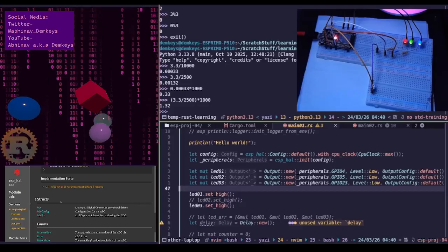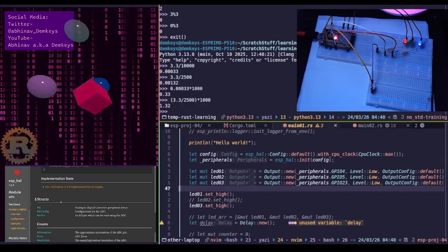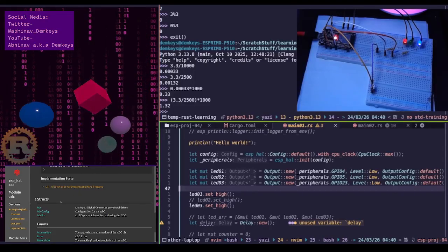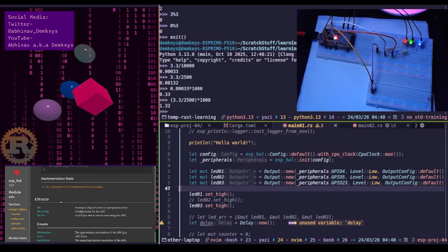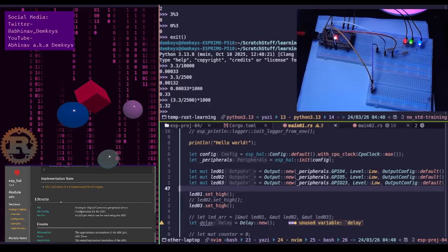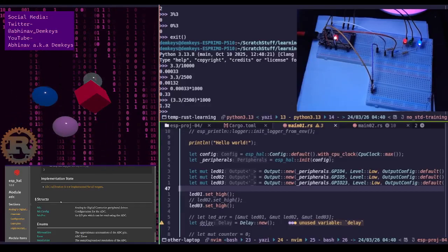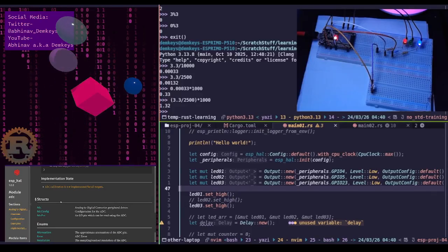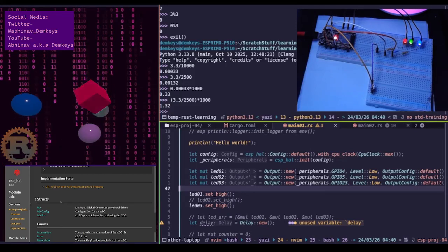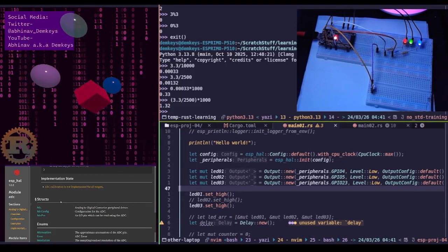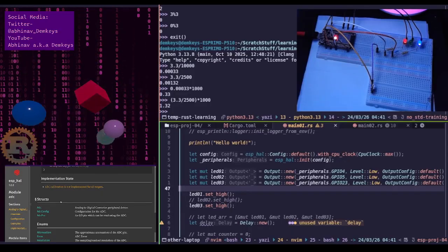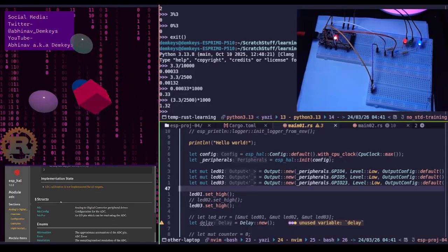Anyways, okay. You are exactly right. A voltage divider is for information, not for power. In the world of microcontrollers, we use them almost exclusively as sensors. The loading problem, why it fails for power. The reason a voltage divider doesn't work for powering things like a motor or a bright LED is that the device you attach becomes part of the math.